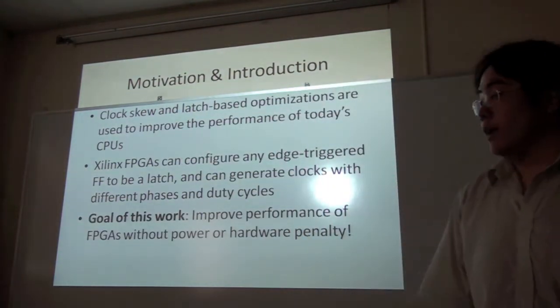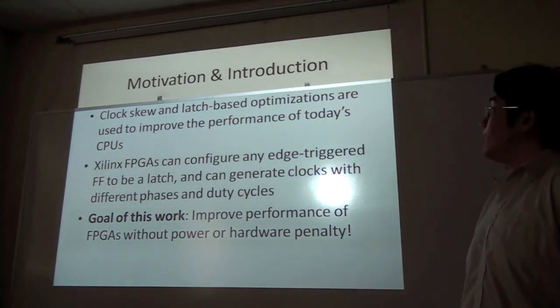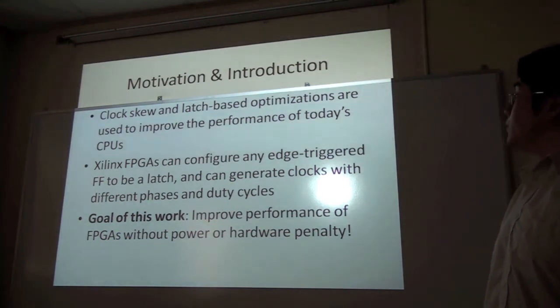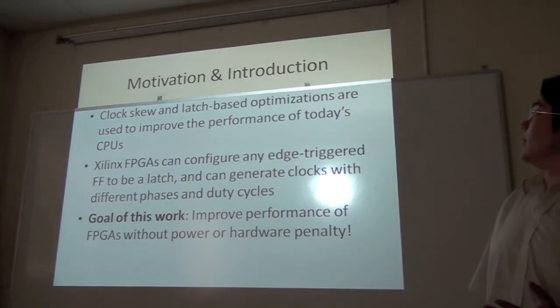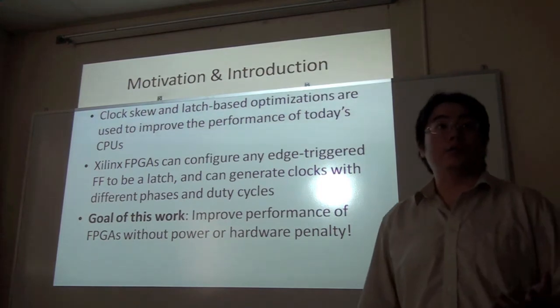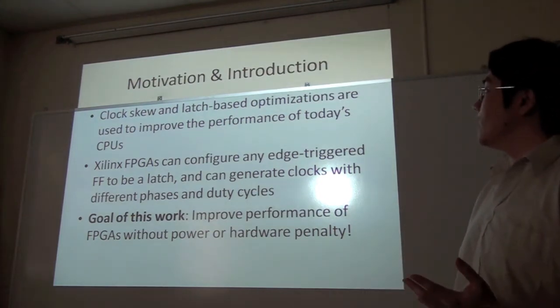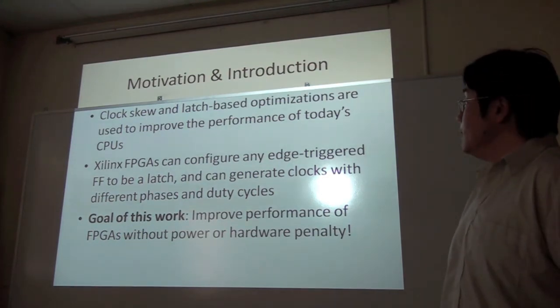One of the ways that has been studied so far, at least, is how to use clock skew and latch-based optimizations. These are used in today's high-end microprocessor designs, and they help these designs reach, for example, 3 gigahertz.